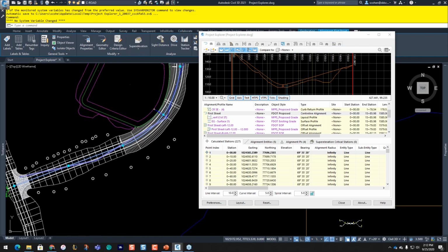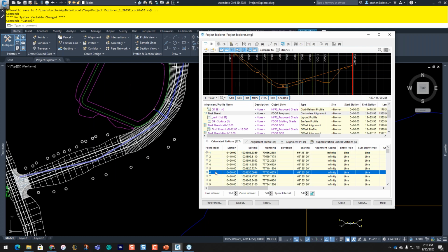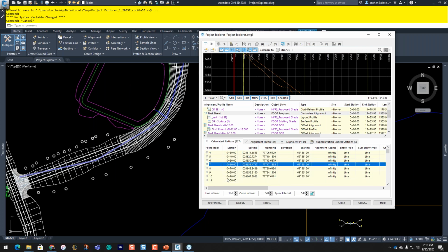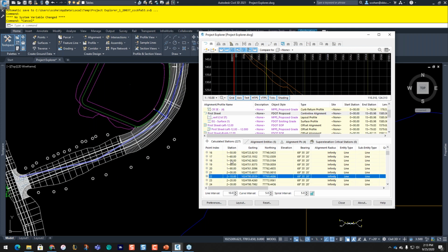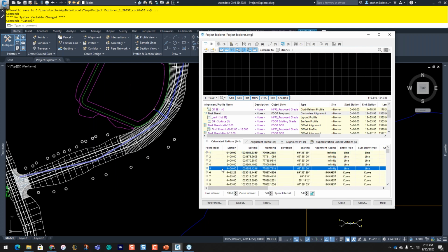Now, to take it a little more granular, what's really nice about this is you'll notice that when you select the object up here, you have this additional option here, okay? A listing of what is contained, like the sub components, or every 10 feet. You can see it's listing every 10 feet what's going on. Now, as I click through here, you'll notice what it's doing in the plan view up here. It's actually updating, which again is really nice. It's just showing you where you are every 10-foot increment, okay? And of course, you can adjust that. Right now, it's showing you the interval right here. If I do 100, now it goes to every 100 feet, right? So again, it's just a really nice little feature showing you back and forth.